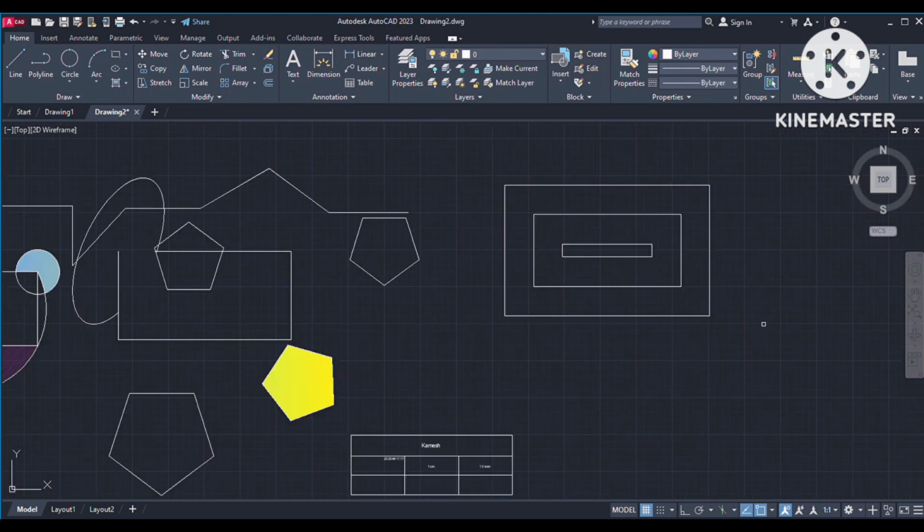If you want inside you can make it, if you want outside just click on the rectangle, automatically click offset command. Now, I want to draw one line between the center, for example. If you use the offset command, we can't, because we drew a rectangle. If you use the Explode command, click rectangle and enter. That means this rectangle will split line by line. For example, if I use the offset command, for example 5 distance I want, click this line, then it will come here. If you want outside you can go outside.